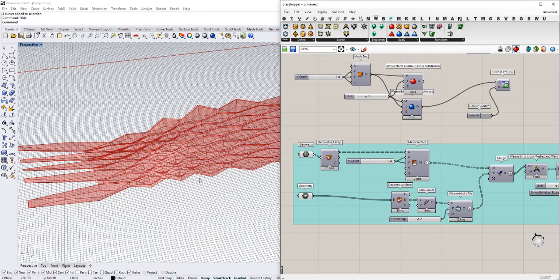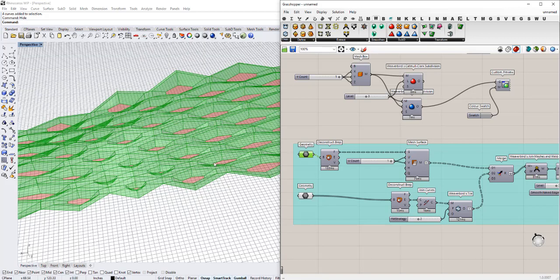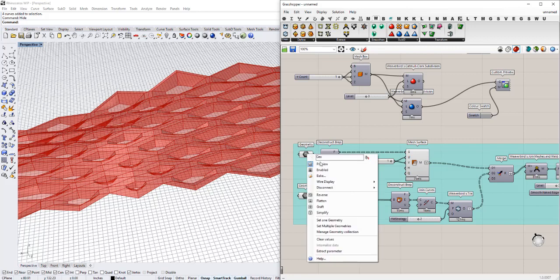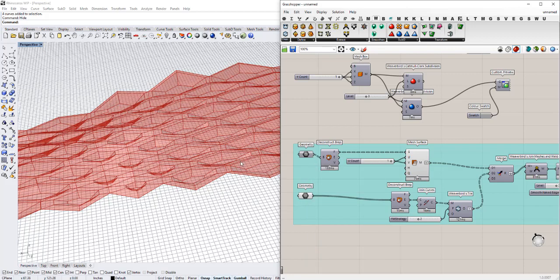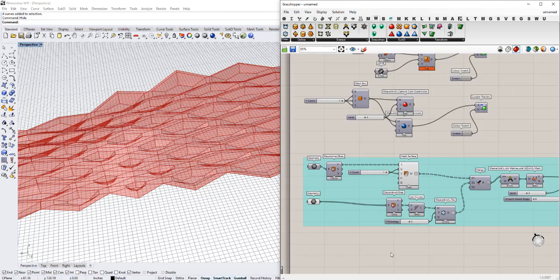If we just treat this as all one system, and we wanted to convert that into a mesh, well, the frame system is all quad type elements. So we can split that up using a deconstruct and make a mesh out of that with single mesh faces in the U and V direction. So that's a pretty simple conversion.